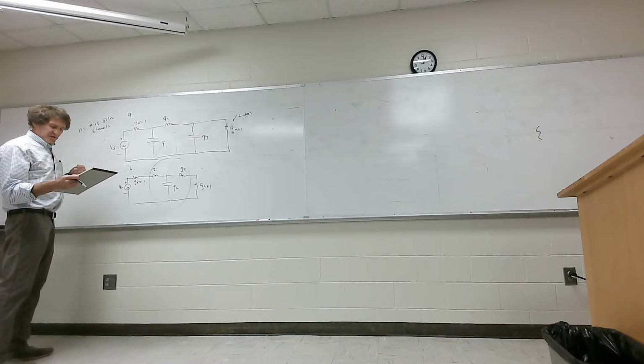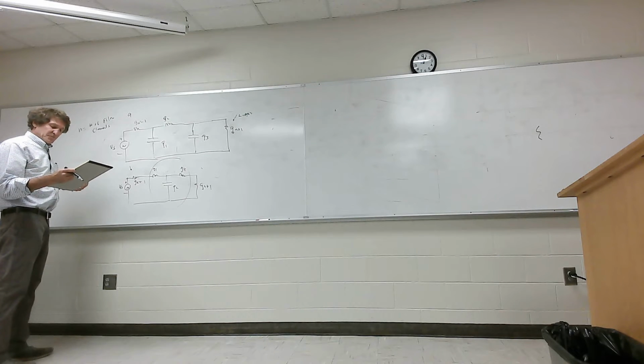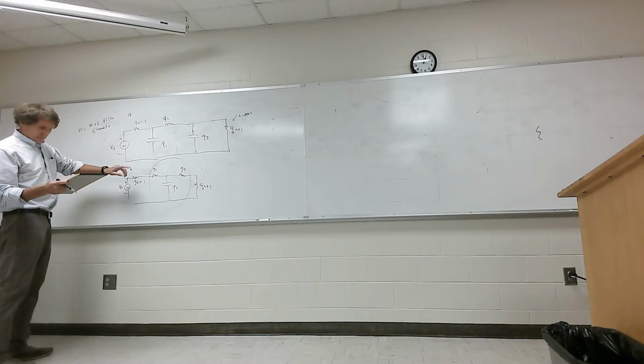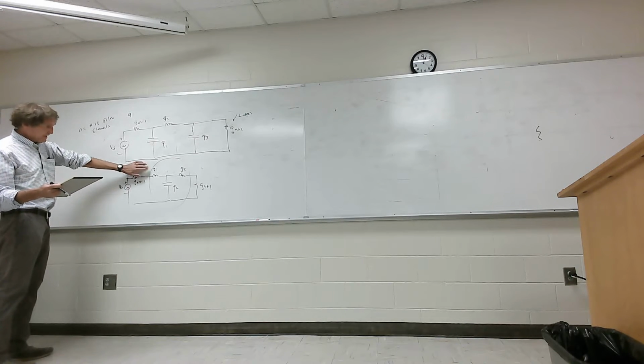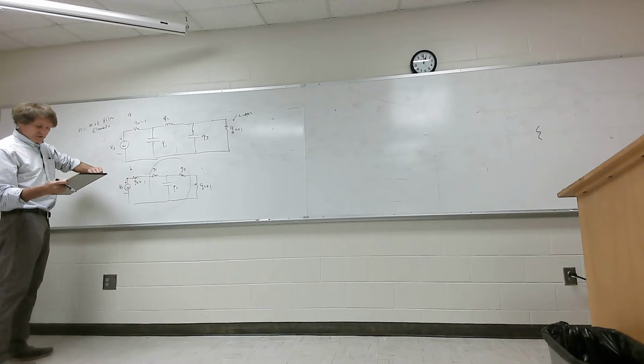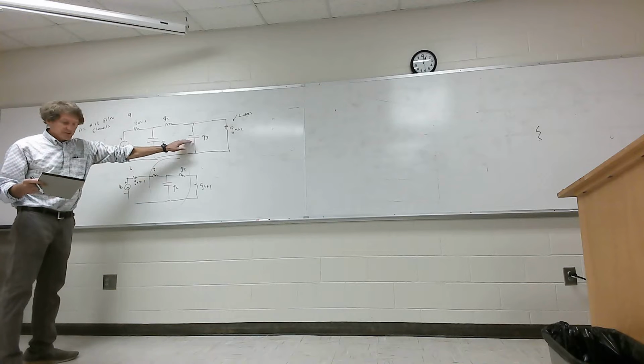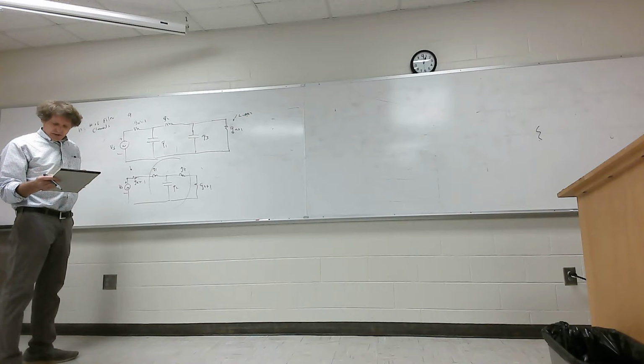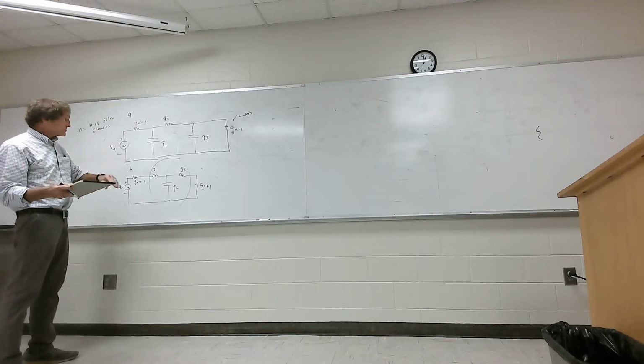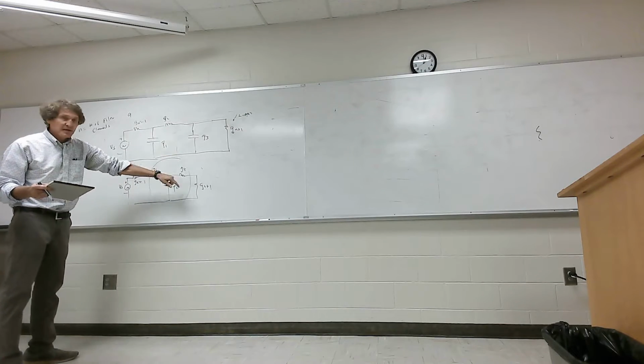Then the second thing is, G1 is an inductance for the series inductors, or it's a capacitance for the shunt capacitors here and here. G N plus 1 is the load resistance, or the load conductance, so it's resistance up here, and the conductance here.